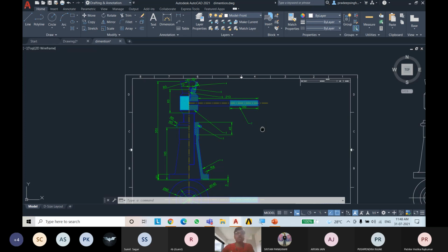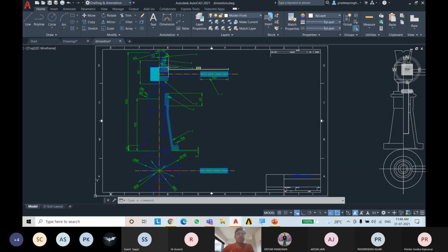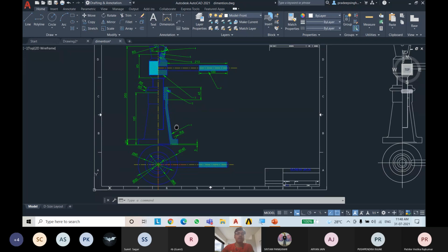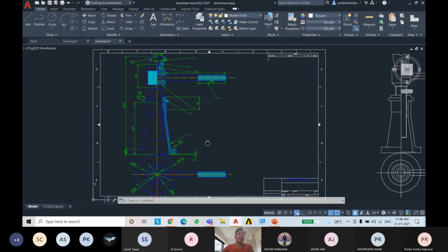this is known as hatching. I have drawn this in a crayon color, and you can see that I have hatched just this part of the drawing, but not this, because in the real world, you can imagine a red line going there and cutting here. So we have used this section plane, and we have cut this part of the drawing and pulled it out to see the inner parts of this drawing. It's used in second years and in colleges, so we can see the inside parts of the drawing.